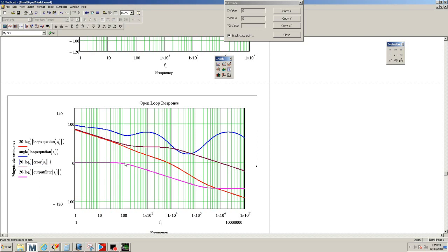And remember, when we do the loop compensation, we try to match this 0 with this pole. So we match it, and there should be a 0 here, but I think because of the gain of the OpAmp, it does not match. See, here's the pole, here's the 0. The 0 should be over here on the error amp, but the OpAmp doesn't have enough bandwidth or gain.